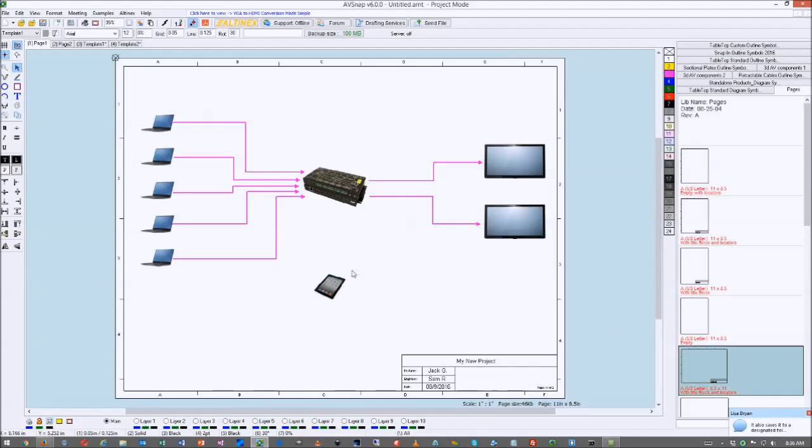You can do a couple of other things, and we'll finally take control and do the line here for control purposes. If you press Control key, it will restrain your line, and you can draw it perfectly straight. If you don't use the Control key, you can draw it at any angle, but the Control key will lock the line into the angles that are shown right here on the bottom, 30 degrees in this case.